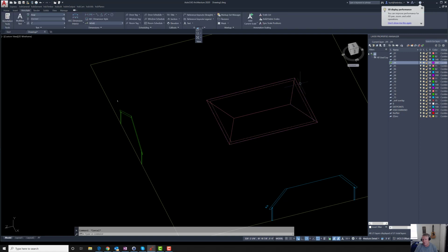And what I want to do now is start creating these roof planes that we've defined here in 2D. We figured out in 2D, and they're projected down onto the ground. I want to create those up in 3D so that I can just throw some hips in and have points to snap, pick down at the bottom here and at the top here, so that I can throw that hip in 3D space.